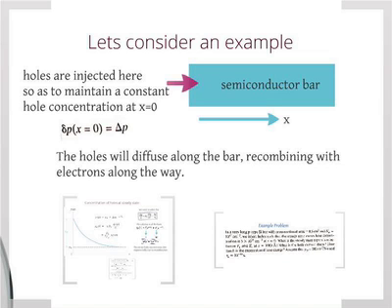As soon as this happens, you get a huge jump here, right at x equals 0. So you have a concentration gradient, a very high concentration of holes right there. So they need to diffuse, right? Go from high concentration to low concentration, which is similar to what you said, but it's the concentration gradient that forces them to diffuse. There's no drift, no field is applied.